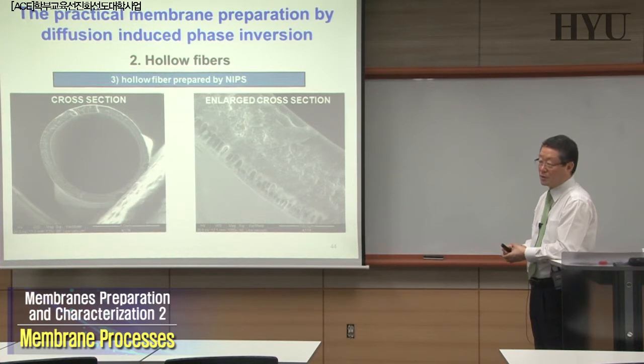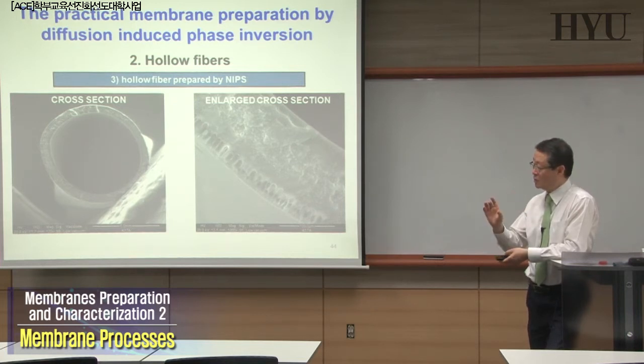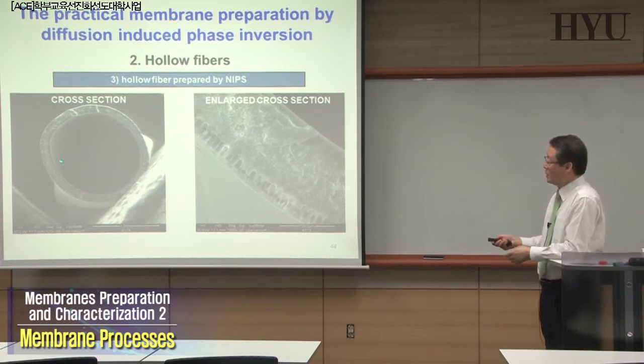Typically, it's about 40 to 50%. So you should have very large walls in many cases, because in gas separation membranes, the pressure will be from 10 to 20 bars, so it should be resistant to that high pressure. If you look at reverse osmosis, then the pressure will be several tens of bars, such as 40 or 50 bars, in some cases 100 bars. Okay? So you should have a certain thickness of your wall. If you're using this membrane for water, such as ultrafiltration and microfiltration, microfiltration has the lowest pressure driving force, which is about a few bars, 4 or 5 bars. Ultrafiltration maybe up to about 10 bars. So with a very thin skin layer or wall, there is no use in industry.